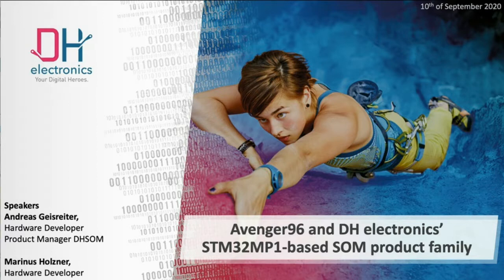Yeah, this is Andreas. The housing and the pinout of the eMMC are standardized by JEDEC, and therefore it works with every standardized eMMC part. So you don't have to use a specific eMMC part from a specific vendor. If it belongs to the JEDEC norm, you can use any eMMC combination with our SOMs.